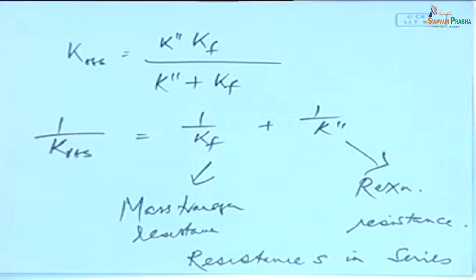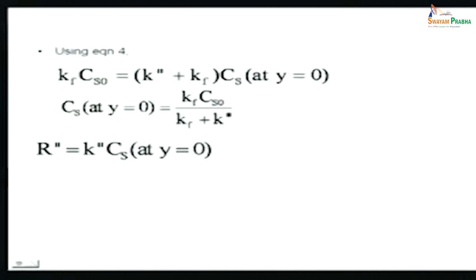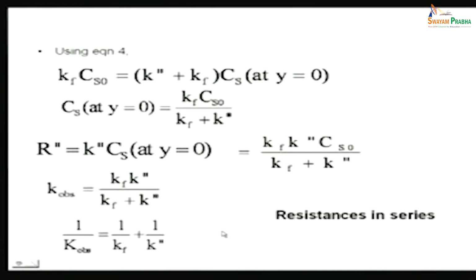So you again figure out that resistances are in series. So, whether it is diffusion or convection does not matter, as long as the processes are in series, you can always add up resistances. Okay. So, just a quick time scale analysis we will do. These are things that we already did. So, no point going through them again.